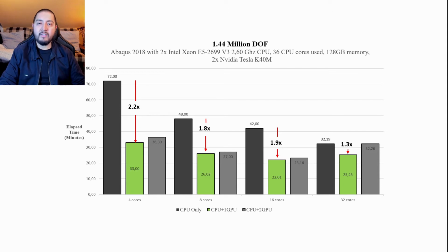Why is this important? Because usually Abaqus takes advantage of graphics cards with high double precision compute capabilities in order to do its job. From my experience, since I made a lot of tests with AMD as well as Nvidia graphics cards, to be honest, after my whole experience, I can only recommend you to use Nvidia graphics cards. OpenCL is also accepted for Abaqus.